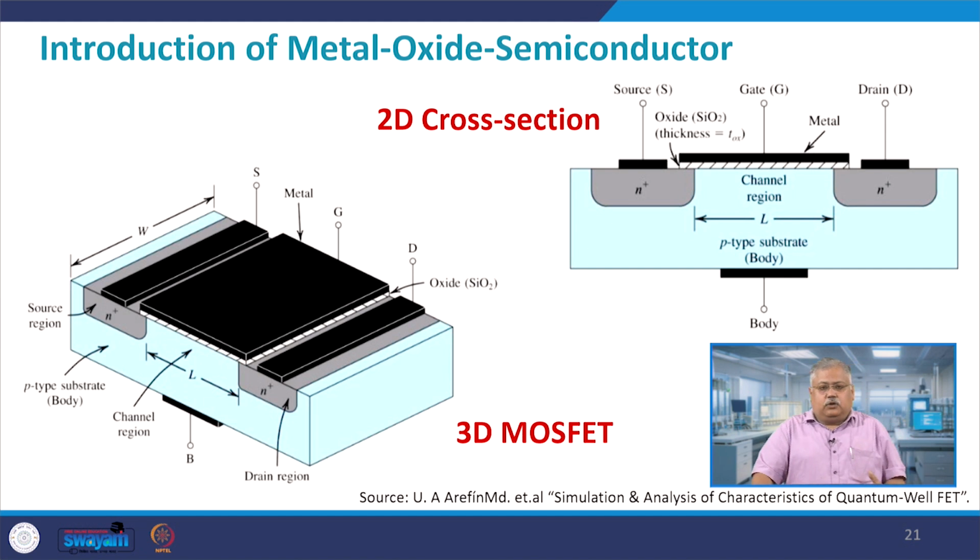You should know these basic concepts before you move forward. Oxidation of silicon is relatively very easy, which means that if you keep a wafer right here in front of you and wait for about an hour or so, you will see a thin layer of white crust over the silicon wafer. The reason is that the silicon wafer will start to oxidize as you keep it in the air. So, the formation of the oxide layer is a very normal and, energy wise, a very stable process. So, the growth is very easy.